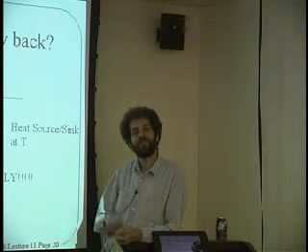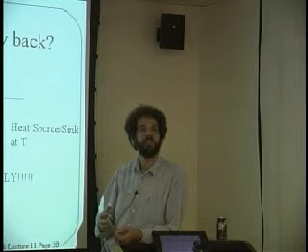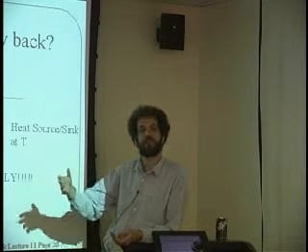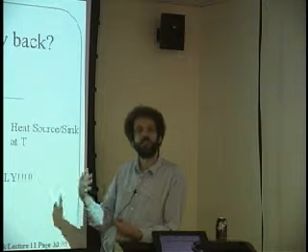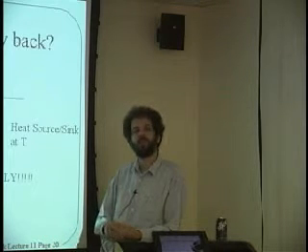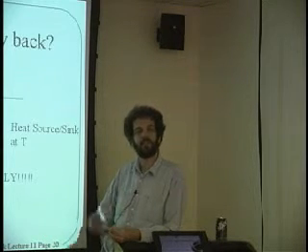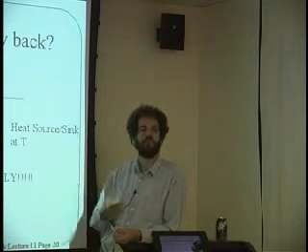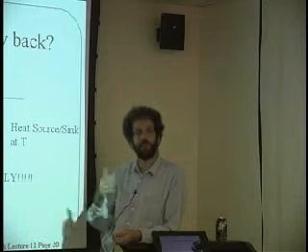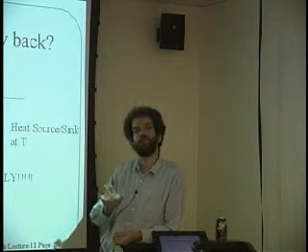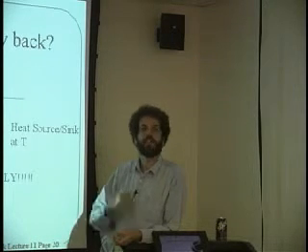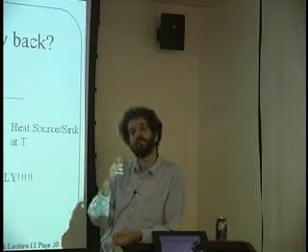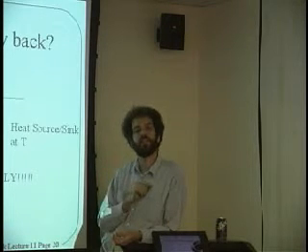And the clutch gets hot, just like the resistor between a power supply and a capacitor gets hot. The momentum of the car, the weight of the car, is like the capacitor, and getting it up to speed is like charging the capacitor up to a certain voltage. And if the engine's going at 3,000 revolutions per minute and you slowly let the clutch out, then the clutch will get warm.